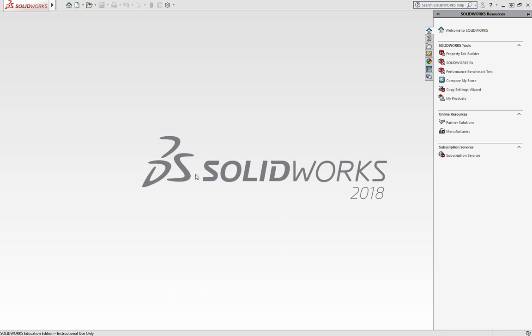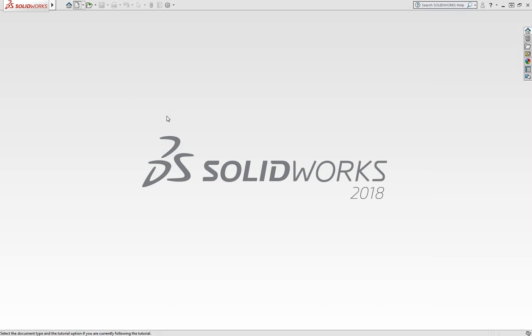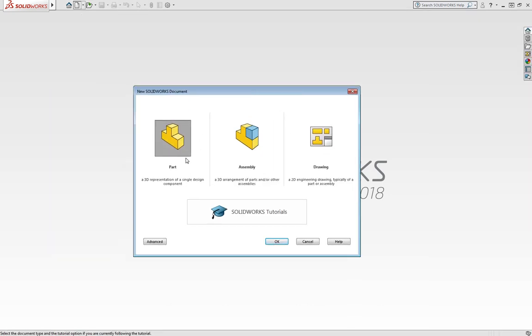So after you open up SolidWorks, you may or may not have a window that pops up here, and if you do, it'll probably say New and Part about right there. If that window doesn't pop up, we can go up here and do the same thing. If yours popped up there, that's fine. Go ahead and just click New and Part. For me, I'll go ahead and go up there. This pops up, says Part, hit OK, and